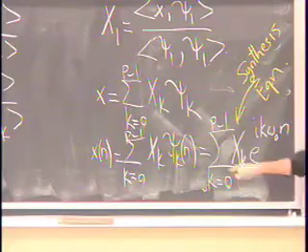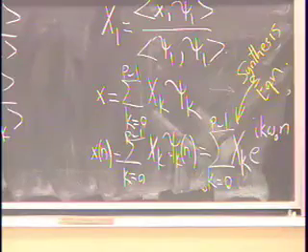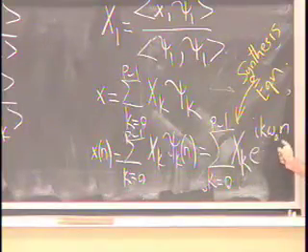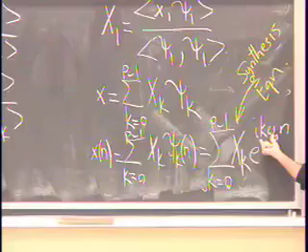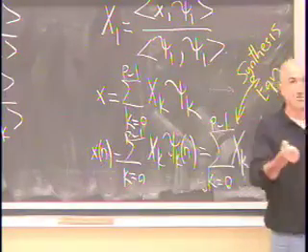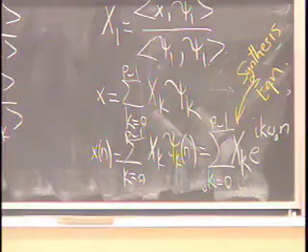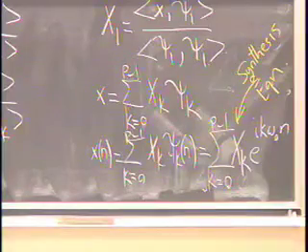It tells you how to synthesize the signal x in terms of a bunch of complex exponentials. These complex exponentials are harmonically related to each other. The only frequencies that can be present in this signal are 0, omega naught, 2 omega naught, 3 omega naught, all the way up to p minus 1 omega naught. You can't have any other frequency aside from these.